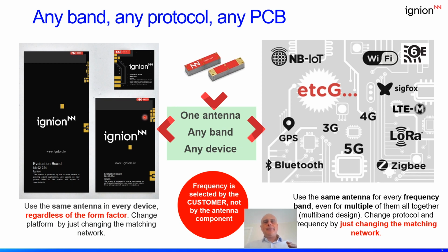So as you can see, designing wireless devices, IoT devices, embedding virtual antenna is a totally different approach. It's not the antenna that determines the frequency bands of operation, but the designer who freely chooses the frequency to operate at, thanks to the design of a matching network.